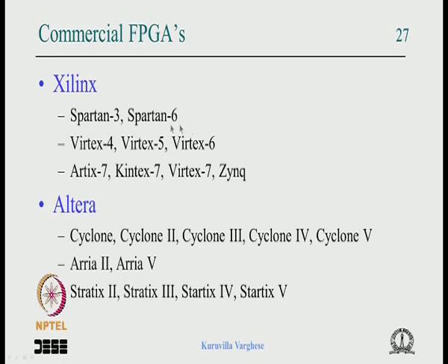It is low cost, but that doesn't mean it's low complexity or low performance. It may lack some inbuilt processors and hardcore blocks in certain devices, but these are still powerful, and they have the complex FPGAs. The previous generation was called Virtex 4, 5 and 6, and the current generation has Artix, Kintex and Virtex, which all share a similar architecture, but they have certain additional resources which are suited for the IO requirement or signal processing and so on.